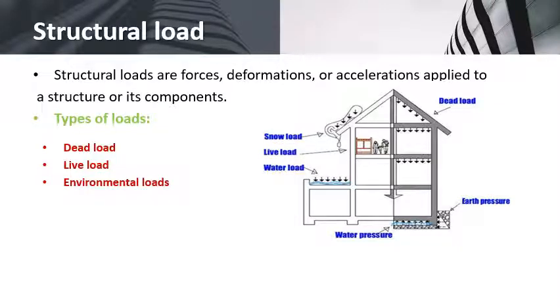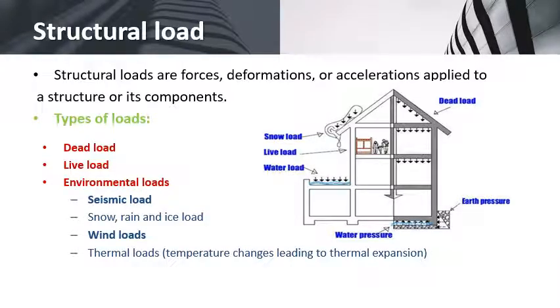Environmental loads are loads that act as a result of weather, topography and other natural phenomena. These are seismic loads, snow, rain and ice loads, wind loads, and thermal loads like temperature changes leading to thermal expansion, and lateral pressure of soil and groundwater or bulk materials. The most important are considered to be seismic loads and wind loads.